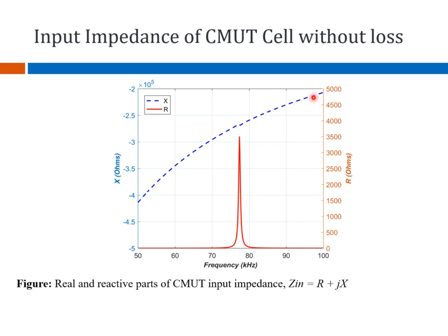the capacitive reactance, and the capacitive reactance, as you can see, is more dominant because of the structure of the CMUT. It's a capacitor primarily. It's a non-linear capacitor having a non-linear relationship with the charge and the voltage, right? So predominantly they're capacitive always. But yes, you have a very high Q peak, which is representative of very low loss in the device.